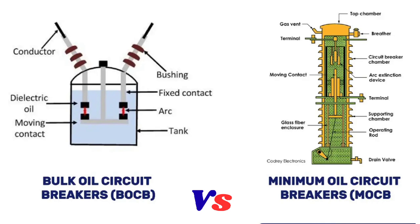The design of minimum oil circuit breakers requires careful consideration of the arc quenching mechanism and insulation requirements, as well as the minimization of oil volume. When it comes to applications, bulk oil circuit breakers are often used in high voltage applications, where reliability and simplicity are critical. Minimum oil circuit breakers, on the other hand, are more suitable for medium voltage applications, where compactness and efficiency are important. So, these are all about types of oil circuit breakers.